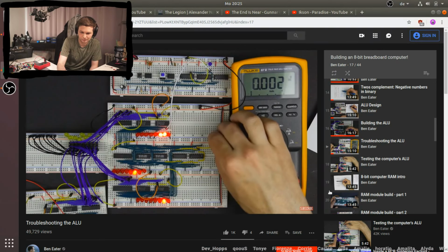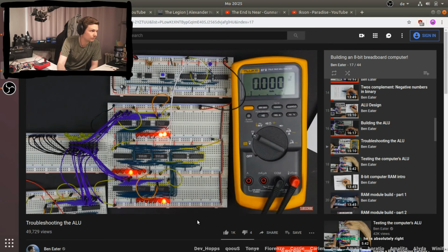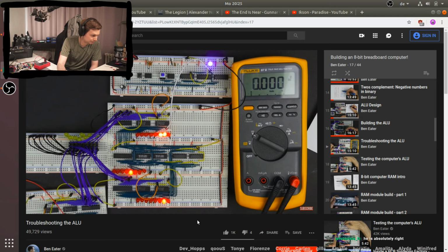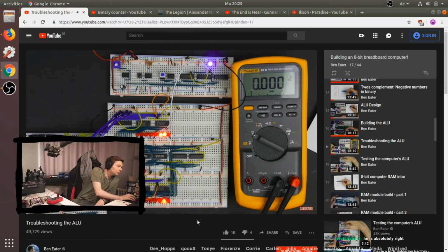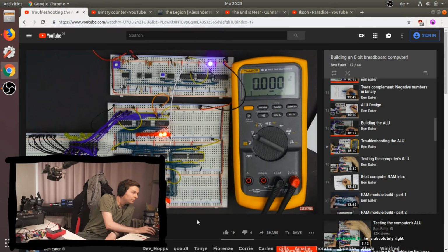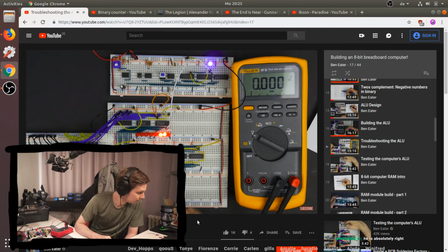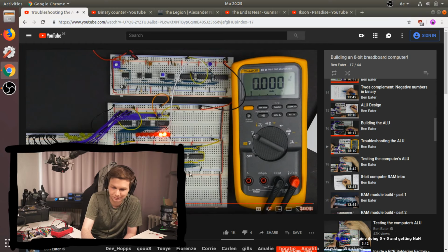And we could try our subtraction. We could see that 0 minus 0 was also 0. And then working through each bit. Maybe that required a little bit of intuition of what the problem might be, maybe that came from some of my experience, just knowing that an easy thing to screw up here is getting some bits mixed up, or if one wire was off, then it would affect one bit. And so just methodically going through each bit on each register and making sure that we got the expected result. And it's important to have a way of troubleshooting things that's methodical and where each thing you're doing gets you a step closer to better understanding what's going on.